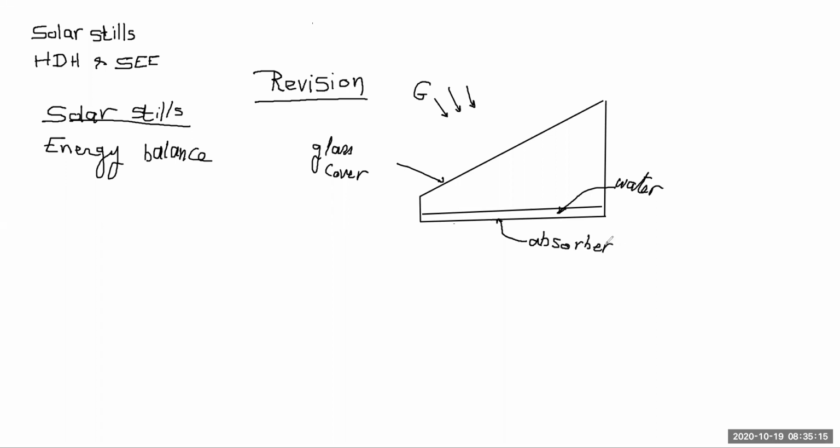In many cases, the idea of operating solar collectors, especially the flat plate collector that is used for heating water, is that it should have an absorber, which is a metallic black painted surface that is heated, and then upon heating, it transfers the heat to the water by convection.